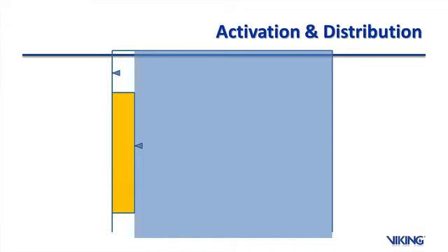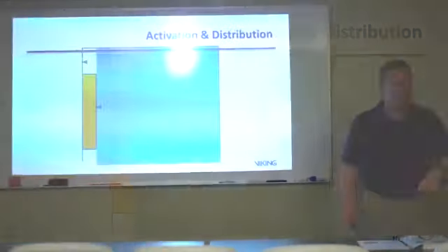Okay, it's spraying over here. The problem was people were saying, oh no, you're creating a shadow area in that space, so we've got to put another sprinkler here. No, that's why we have obstruction rules. That's why part of this presentation is looking at the obstruction rules that we have, because we've known about them, and we detail this, and it's why, because the concept of fire control in most of our systems, most of the systems we design, is very important, so that we don't have to be putting sprinklers behind every pole. All right?